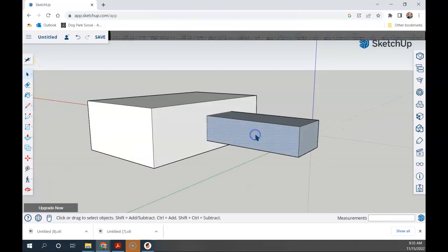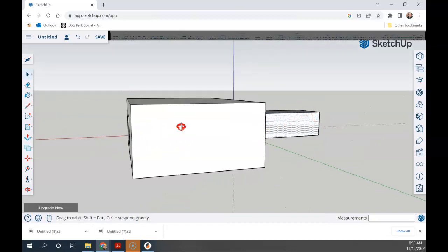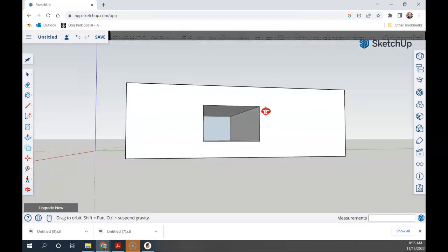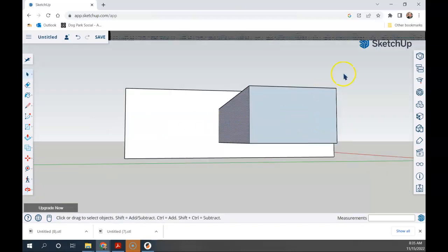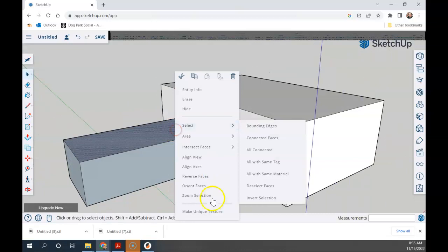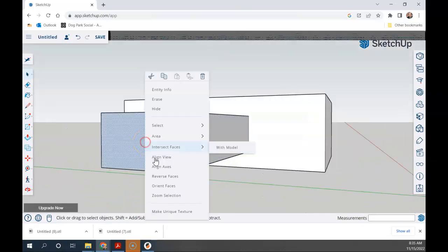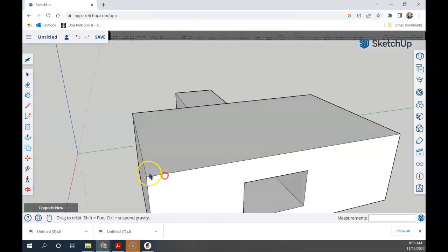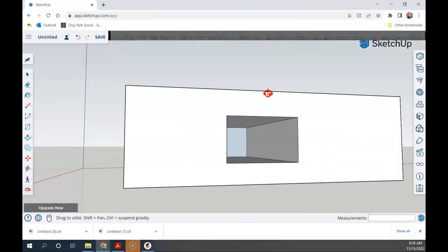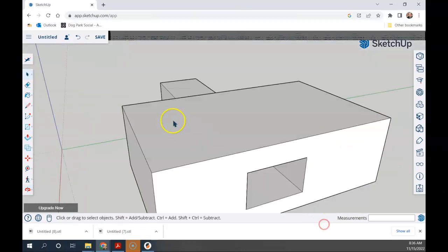And then we also talked about reversing faces. Be wary of what that's going to do on the inside. It looks like it's okay because I created those extra walls, but I'd have to reverse all these faces in order to make this work. If you're running into problems, it can sometimes be a little tricky. Definitely ask for some help to make sure that your model is printable. And there I should be okay. Let's see, is that the right one? No, there we go. Perfect.